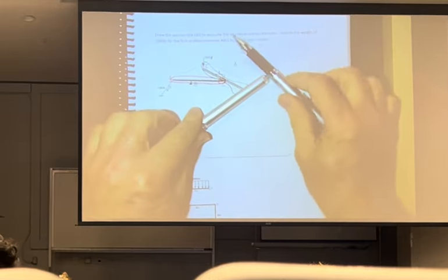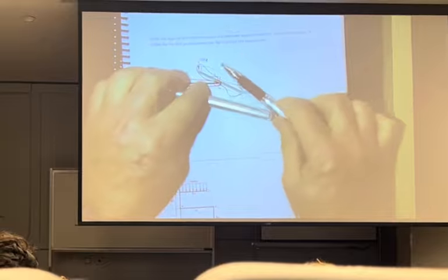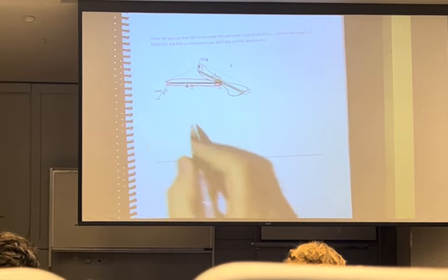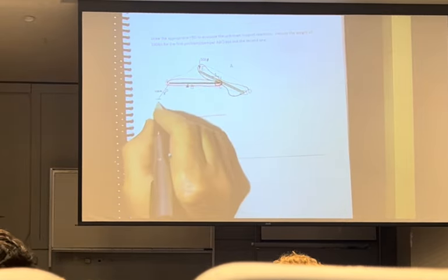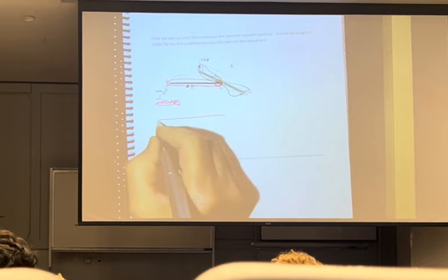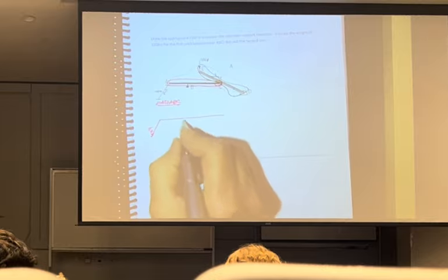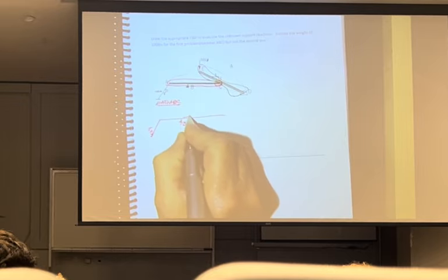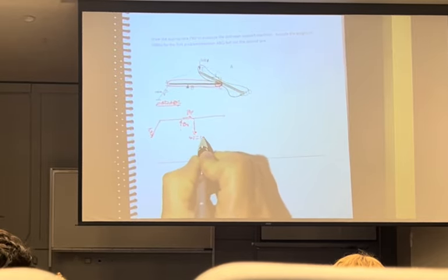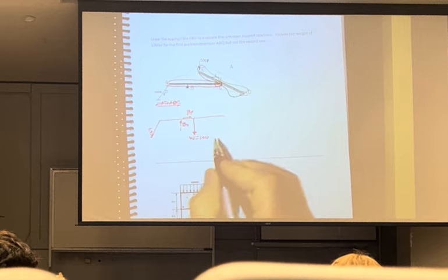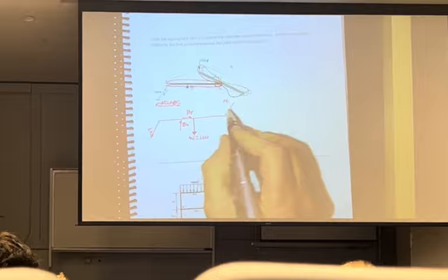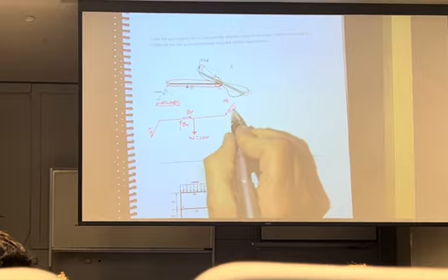So this is sitting like this. So this is pushing down on this member. This member is pushing up on that member. That's a normal force. So my free body diagram of A, B, C will look like this. Cable tension TA. I have a BX, BY, solid member W is equal to 100 pounds, I will have a normal force NC, which is at 2, 3.